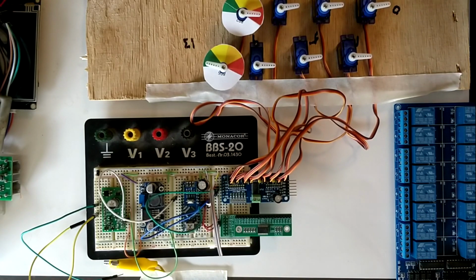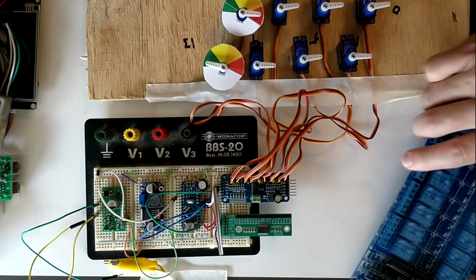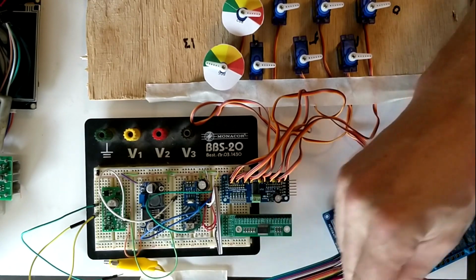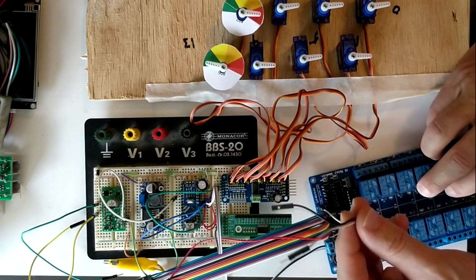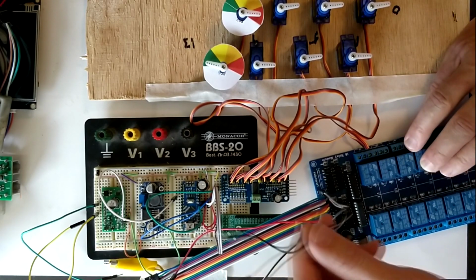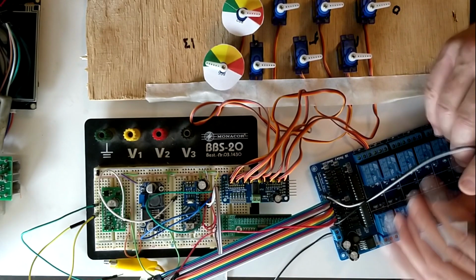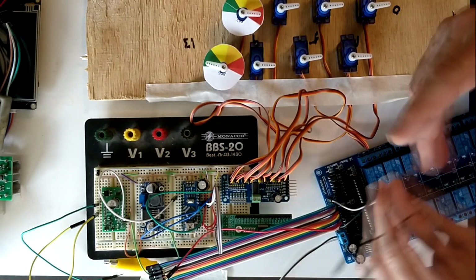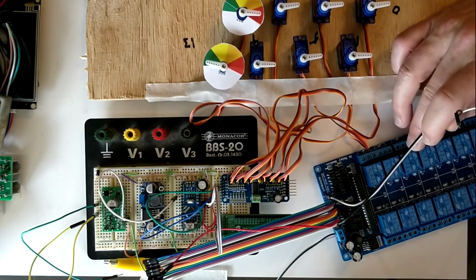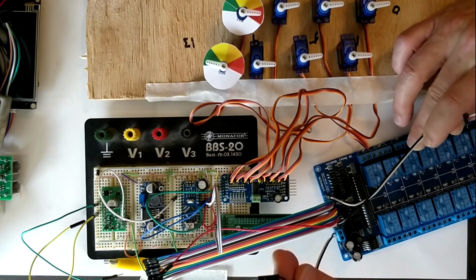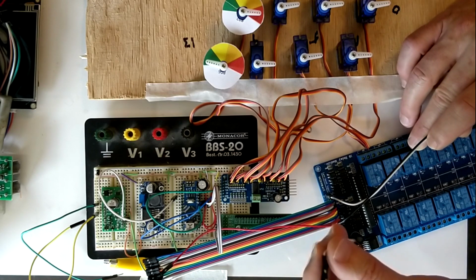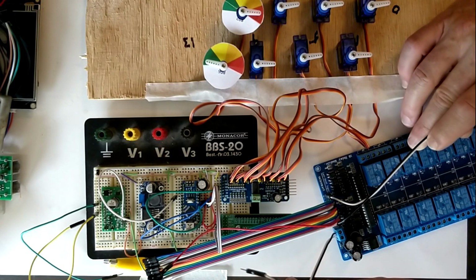That's it. So now for the relay board, and I have already prepared that. It requires 5 volt and ground, so VCC and ground, and that's for the logic. And for driving the relay coils, it requires 12 volts. So 12 volts, I'm lucky here because the whole thing here is connected to